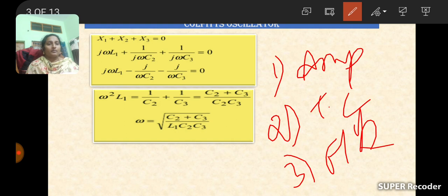It is an RC coupled amplifier containing a potential divider biasing network, R1 and R2, for biasing and stabilization. Coupling capacitors are also there. Cin is used to block the DC signal and pass only the AC signal. An emitter bypass resistor and capacitor are also there; they provide a low reactance path to the signal.